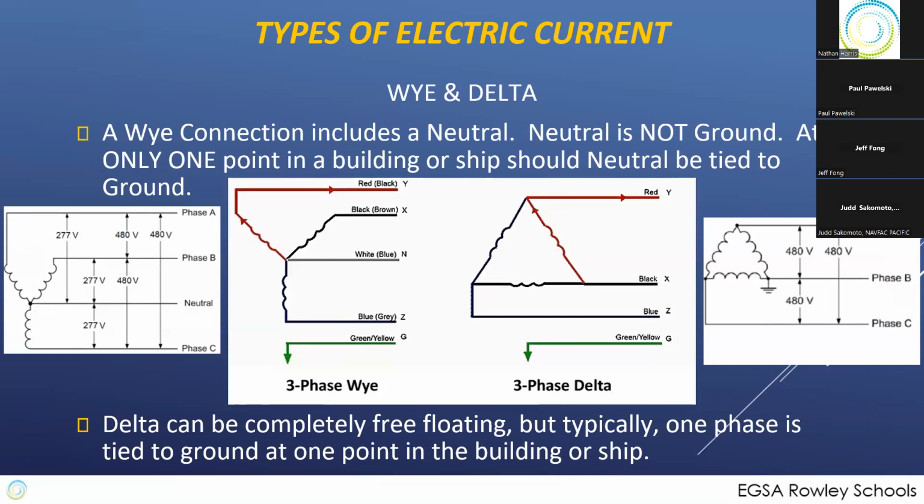On the other hand, most stuff that is sent 50 hertz is designed to EU standards, and the EU standard says they don't have to include a ground strap anywhere, that you are supposed to be smart enough to pick the location in your facility, whether it's on one of the generators or on some transformer or something else, to connect neutral to ground or B phase to ground. So you have to pay attention, especially on deployment activities, because what you're getting might not necessarily be what you're used to.